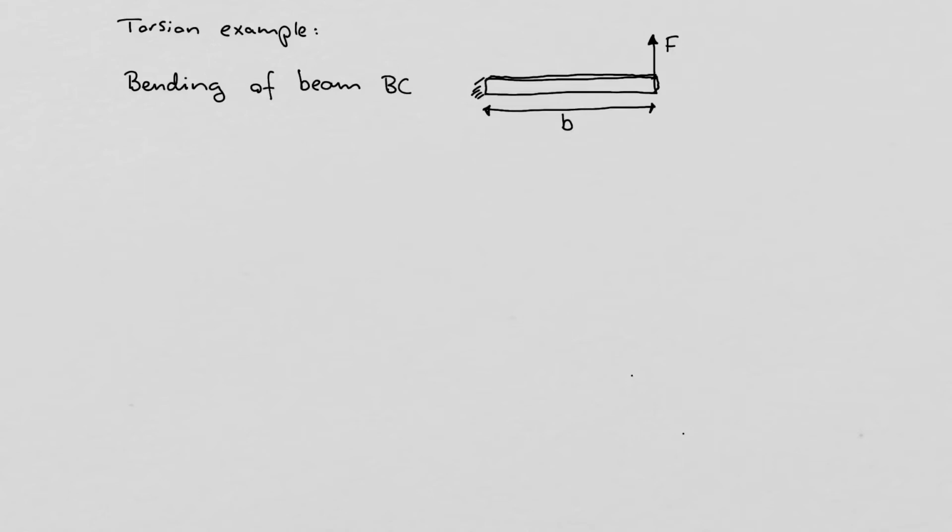Now, this is a standard case that we have looked at quite a lot of times before. It's a simple beam. It has a homogeneous cross-section, a homogeneous distribution, so we can use the elementary cases. And when we look, we can see that we have to use elementary case 6, which will predict what is the vertical deflection of our beam.